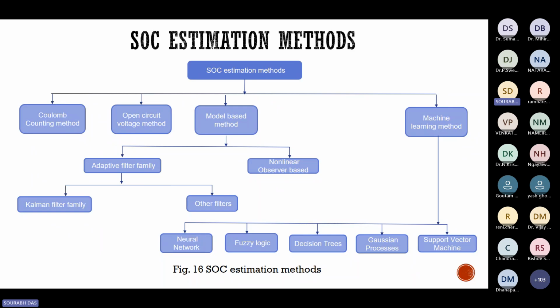So SOC is calculated by measuring the current and then integrating that measured current, and the initial SOC is needed here to accurately estimate the SOC of the battery.